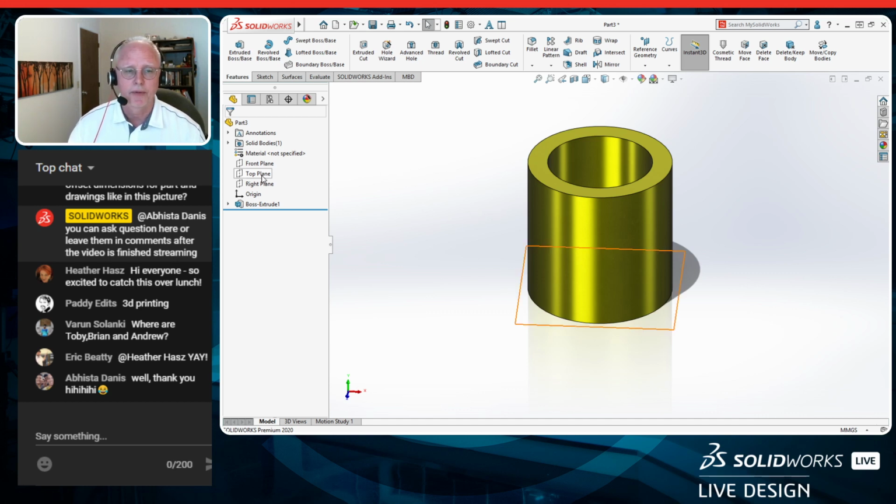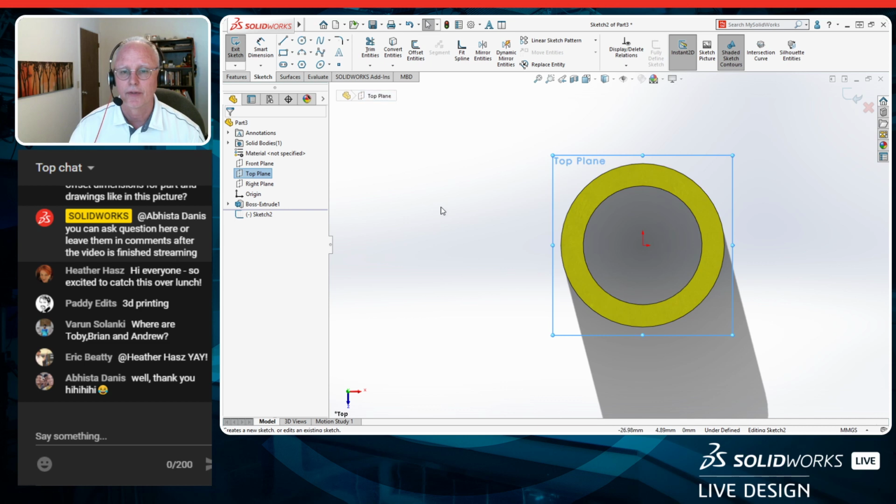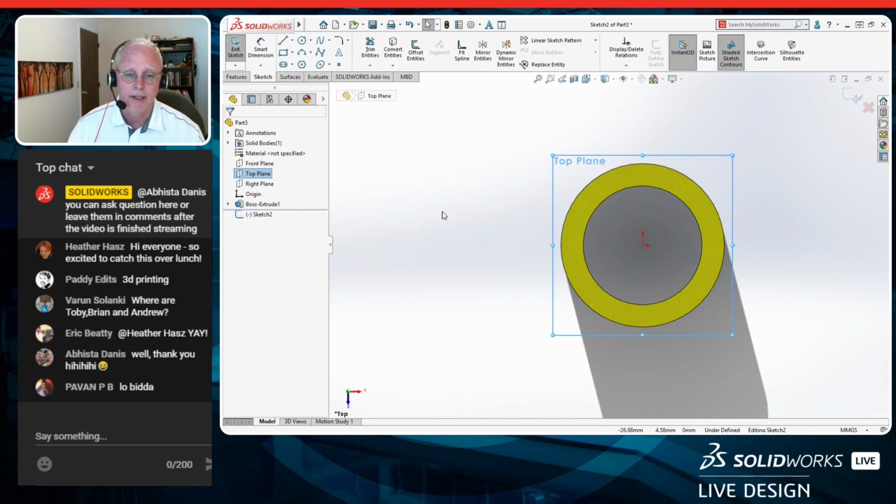So we're going to start drawing in that arm. On the top plane, I'm going to create a sketch. And one of the things you'll notice that I like to use as I go is the mouse gestures tool. You'll see this pop up as I go. Sometimes it goes by so fast you won't even notice it. So be aware that you'll see that. I'll show you how to set that up.